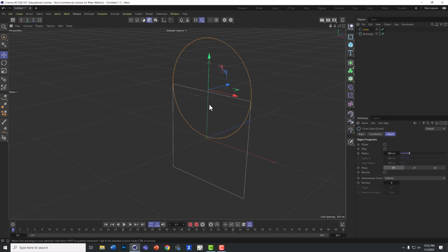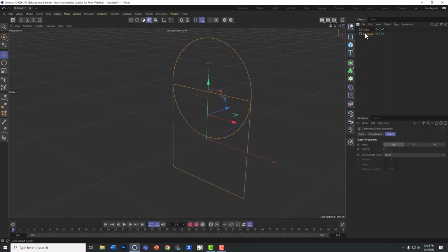Turns out there are some Boole tools for the splines. It's not this one. You have to go to your spline menu. Make sure first that both of your splines are highlighted. Go to spline, Boole commands, and you're going to see pretty much the same thing. This is for 2-dimensional instead of 3-dimensional objects. So let's go spline union. And that's all it takes to turn that spline into one continuous spline. Let's go ahead and extrude that.